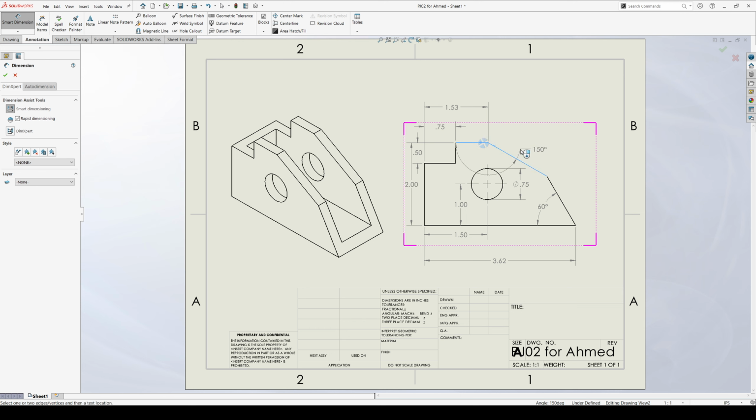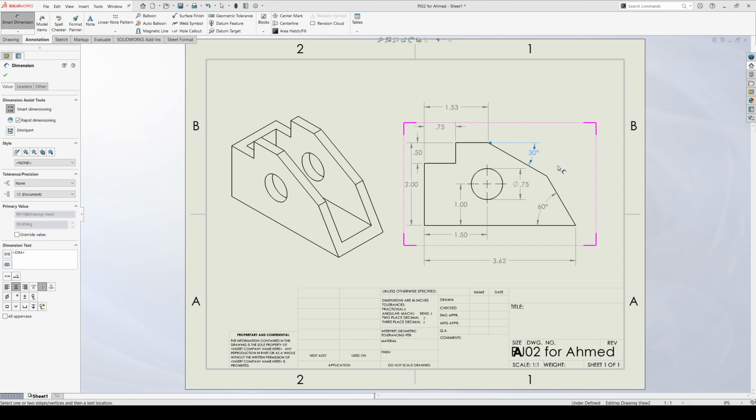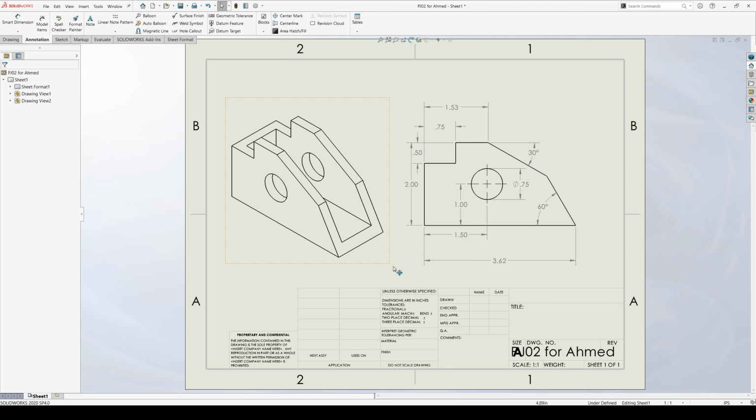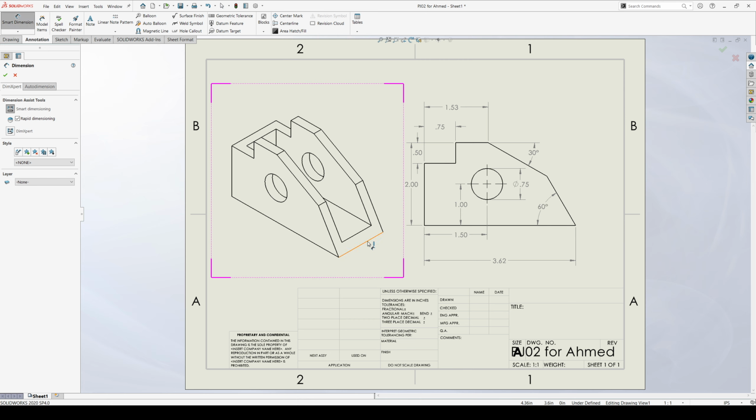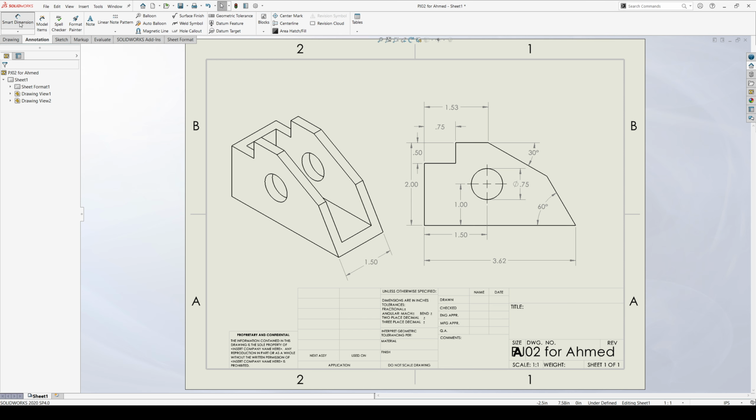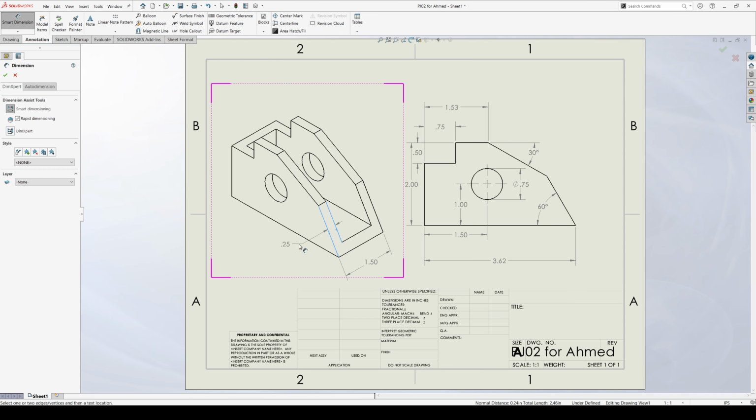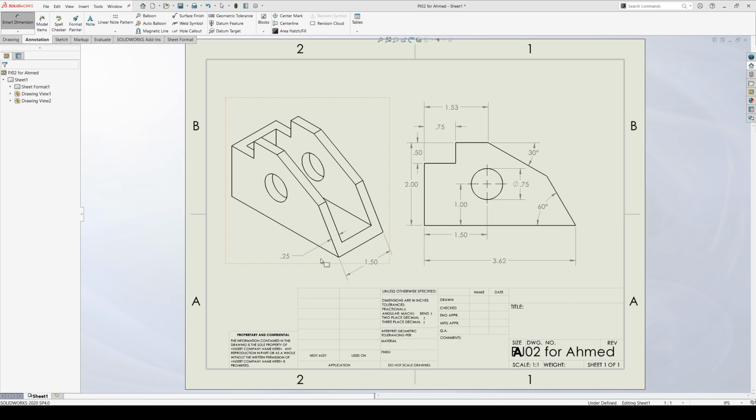The problem here is it's a little trickier to do it in drawing. So, there's an angle, there's the outside angle. You still want this lower outside right here. So you have to find that imaginary line and just drag it around, and there you have it. And there's our dimensional information for the part, but we still need to show the width and whatnot. So you dimension, there's the width of your part. You need to show the thickness of the walls, so there's 0.25 there.